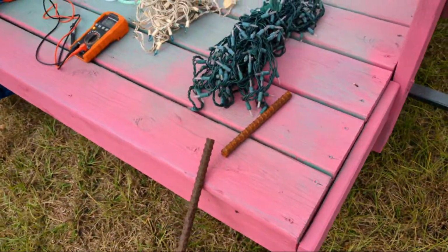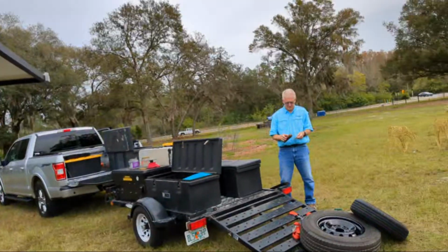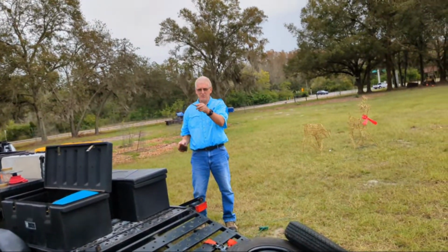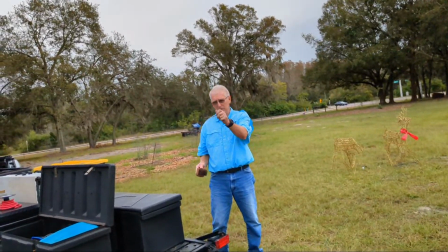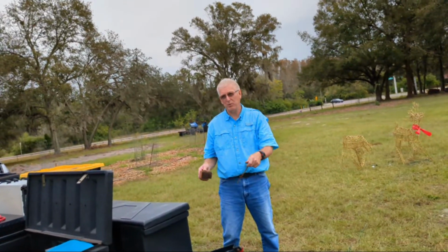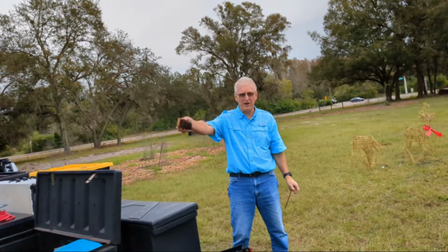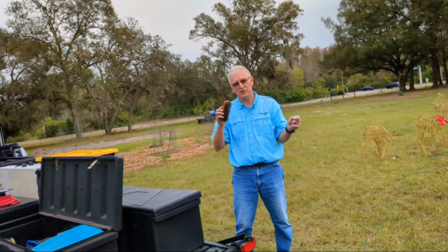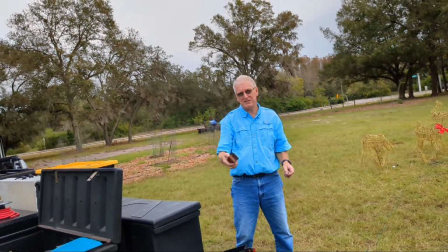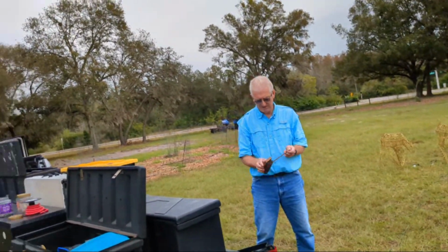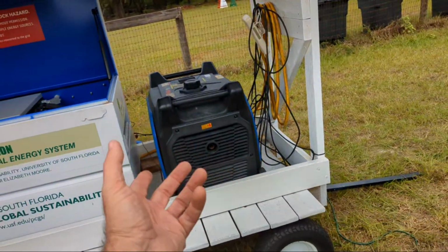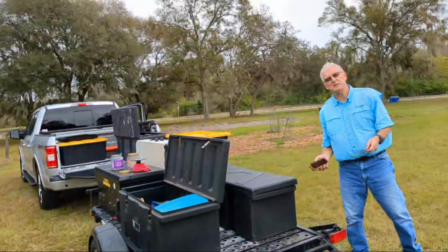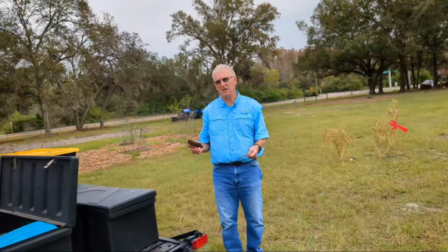By the way, this won't fix the fault, because just because I ground all the metal objects on the power system to earth the way it would be with your ground wire, that does not provide a connection between the neutral and the ground. So we would still get something. You'd always have to have a generator, or you'd have to have it connected to a device that creates a bond between the neutral and the ground.